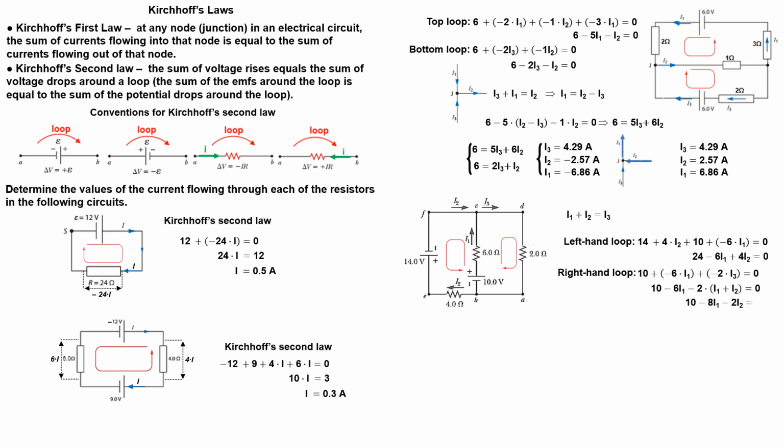We get 2 equations for 2 unknown currents. Solving the system, we find the currents. As a last step here, we correct the answers by reversing the arrows for those negative currents, and then rewrite the answers.